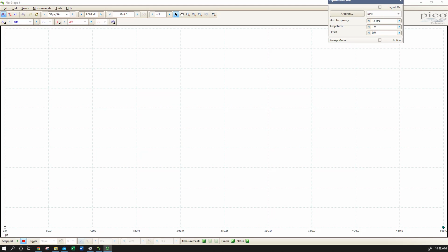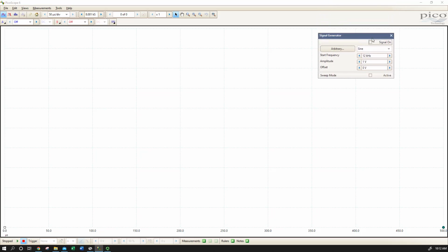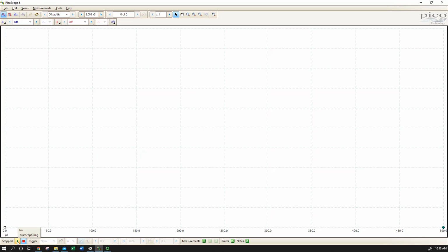Okay, we are back from our small pause, and we are ready to start looking at our frequency-based measurement. You can see my Picoscope screen is still in scope mode, and that's shown by our little highlighted square that shows two superimposed sine waves over here. You'll notice I've stopped the display down here on the lower left. You can see we have a little red square meaning stop, and a green triangle meaning go. This is the capture of signal by the Picoscope and its display.